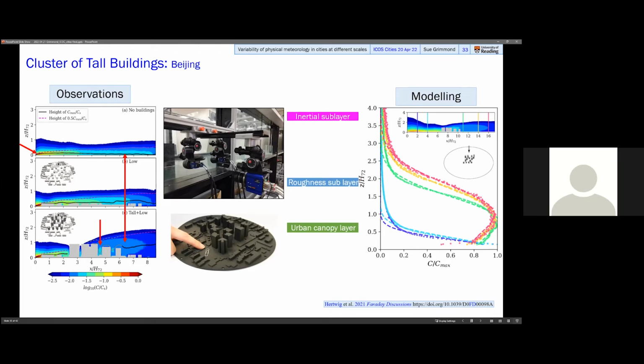One of the models commonly used for air pollution modeling is something like the Gaussian plume model to look at the dispersion. We can see that in front of the buildings the Gaussian plume model can actually work reasonably well. But as we go past the buildings, a simple Gaussian plume model does not work well unless you lift the apparent source. So instead of the source being close to the surface, it needs to be higher above the surface before you can use a Gaussian plume model to calculate the dispersion.